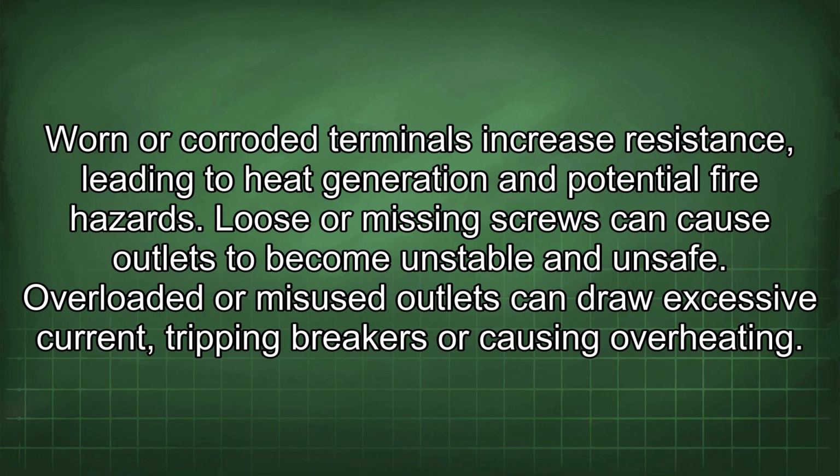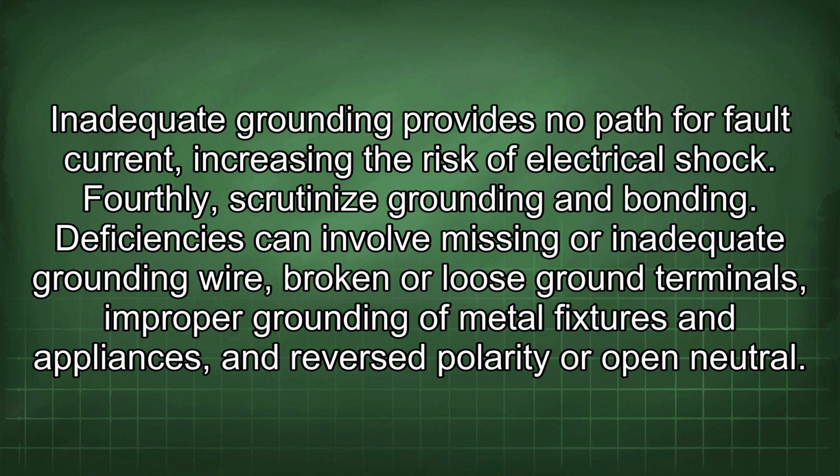Loose or missing screws can cause outlets to become unstable and unsafe. Overloaded or misused outlets can draw excessive current, tripping breakers or causing overheating. Inadequate grounding provides no path for fault current, increasing the risk of electrical shock. Fourthly, scrutinize grounding and bonding.